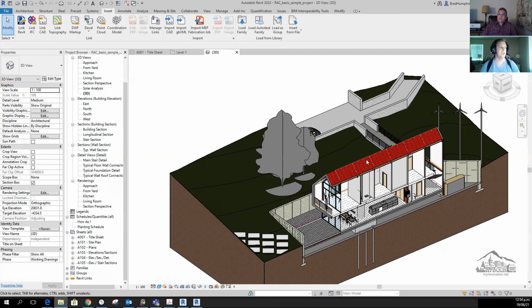So for instance, you can schedule out all of the rooms in Revit, and all the floors that they're on and what sort of finishes they have, and you can feed that directly into your facilities management software. So in our stock, we have something like 270 odd buildings in our portfolio, and probably more than that now actually. And we have Revit models for most of them.